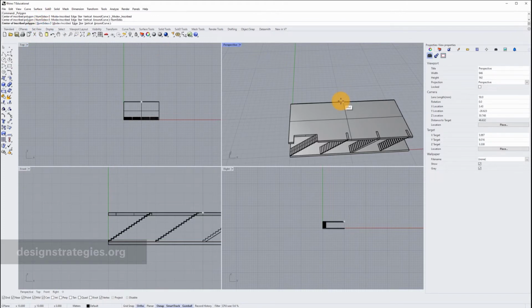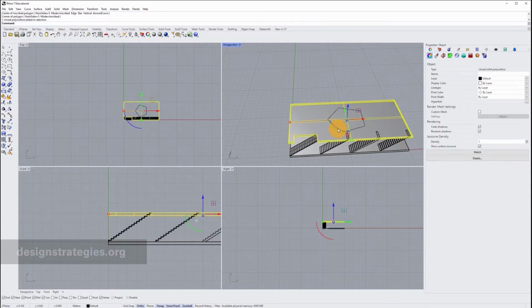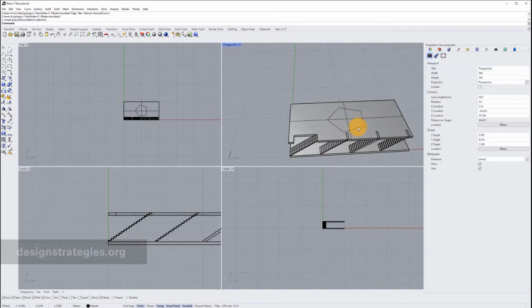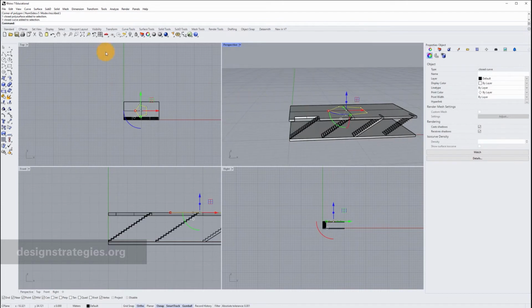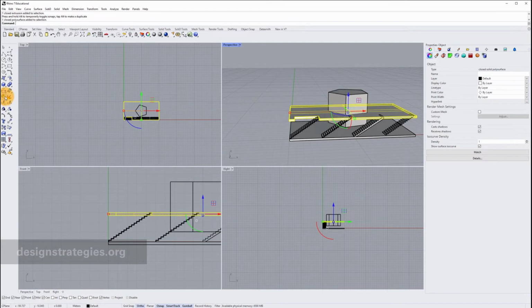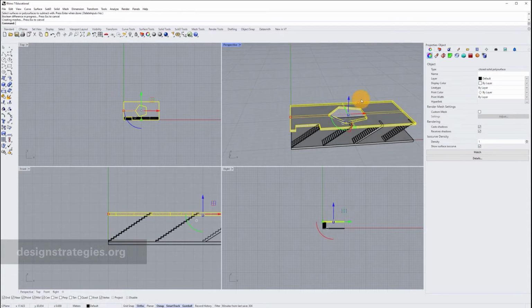And I just go here to midpoint, and midpoint with my smart track function, take the intersecting point of this and just draw my polygon. I just select this actually, okay, I select it, and I just extrude this somewhere like this, and just the principal thing, and I just move this a little bit and subtract my first floor with my hexagon. Okay, here we go.